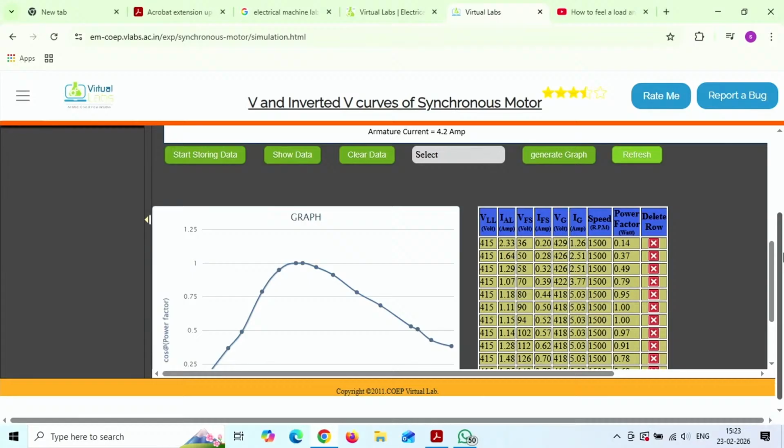Right, Vm sin omega t, minus 120, minus 240, yes, they give neutral. But if such a fault occurs and current is flowing through the neutral, we need to see how much neutral current this alternator can provide, and with what impedance. So that is the experiment. It is showing the sequence operations, to find the sequence parameters.